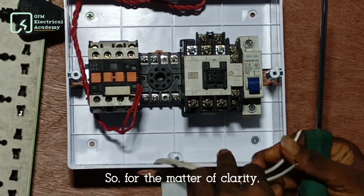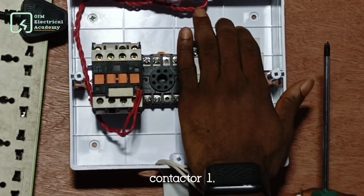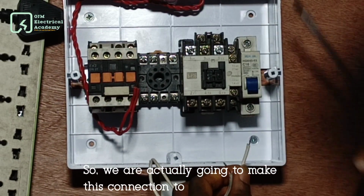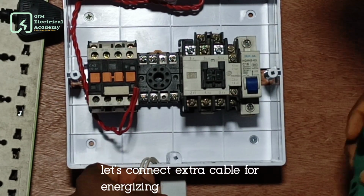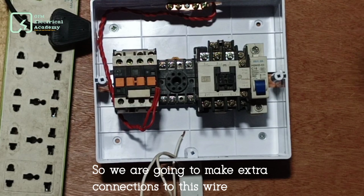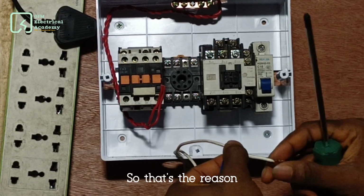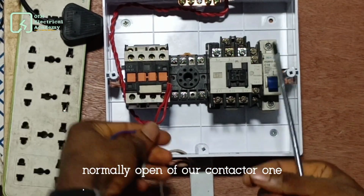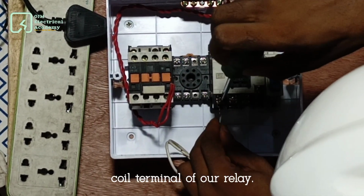For the sake of clarity, this is our utility supply contactor 1, and this is our contactor 2 for our generator or any other alternative power supply. We are actually going to make this connection to this and this. But before that, let's connect extra cable for energizing the coil terminal of the relay. So we are going to make extra connections to this wire so as to connect to the coil terminal of our relay. Remember, we are connecting it to the normally open of our contactor 1, and from there we connect to the coil terminal of our relay.